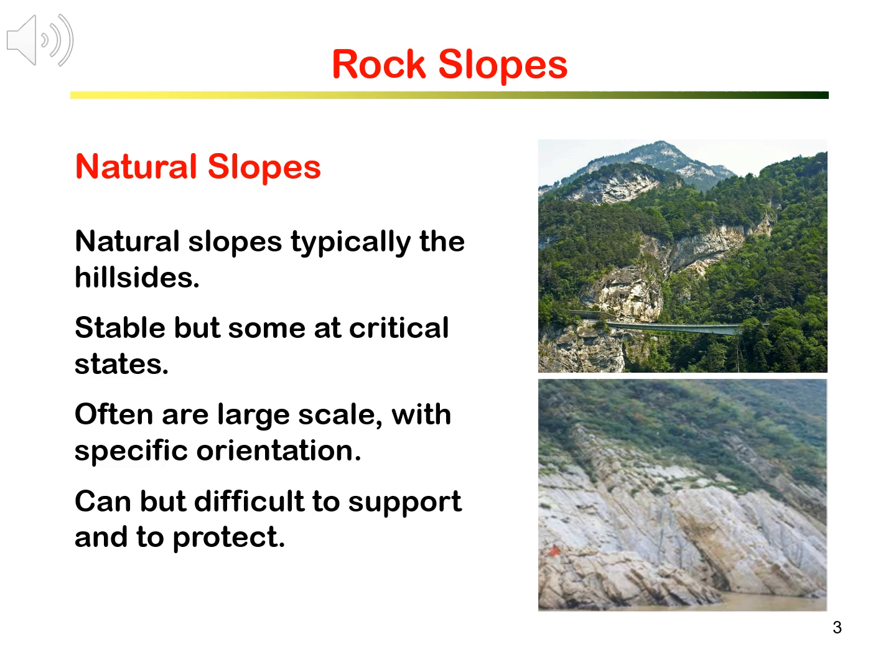Natural slopes are usually stable and existed for hundreds or even thousands of years. However, due to weathering, erosion, and geological activities, some of those natural slopes may be at a critical stage of near failure. That means if they are subject to additional effects and loading, such as rain, earthquake, or other disturbances, they may fail and slide down.